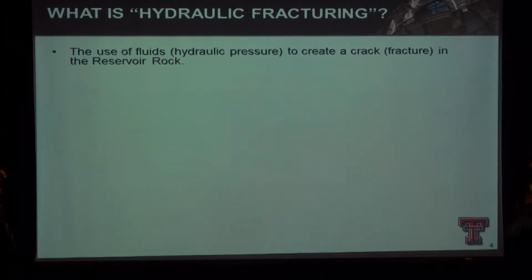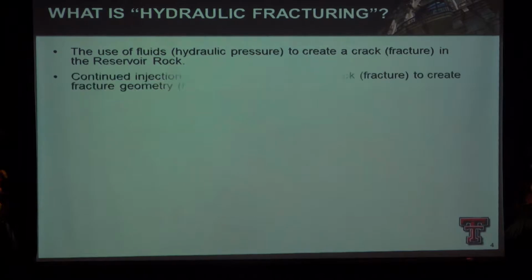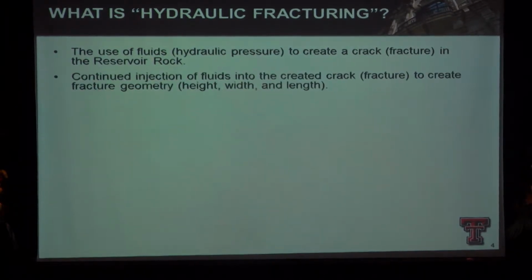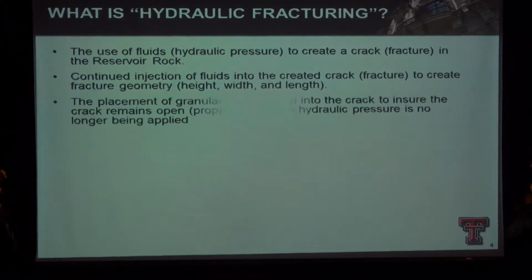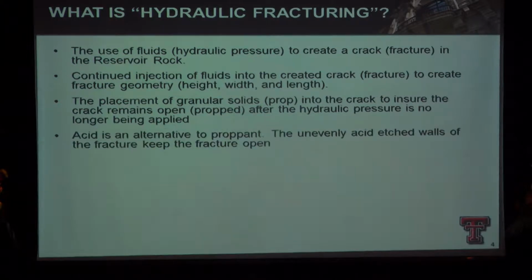So what is hydraulic fracturing? First off, you're pumping water and sand at very high rates and pressures into the rock to create a fracture, a crack. Then you place sand, like you have on your beaches here, into that crack to keep the crack from closing.